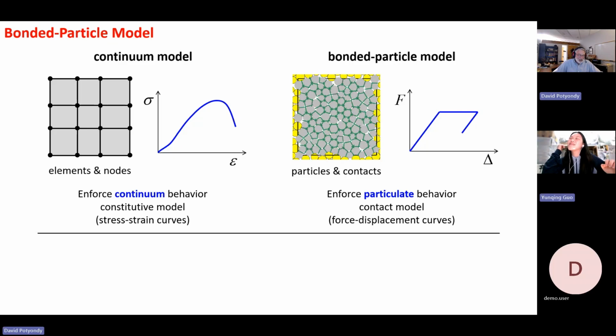Coulomb? Yes, that's called the Coulomb law for frictional sliding. Yes, and that means you have a concept of a friction coefficient that limits the amount of shear force that can be carried. This is awesome that you know about this. That's what I actually drew here. That's one of the very simple PFC breakage models. So this would be shear force, this would be shear displacement. It loads, it reaches a critical limit and it slides. And then if you unload, it does this.